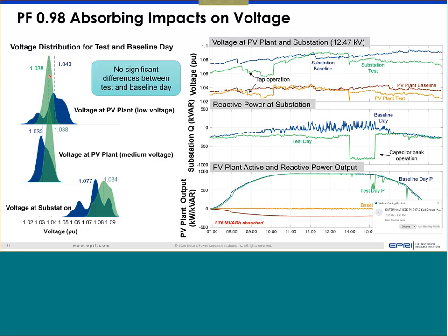Whether the same effect can happen on the medium voltage side, after you go through the transformer and with the other customers around it, how they behave. In this particular case, you can clearly see that's not the case. On this medium voltage side, yeah, it tightened the voltage, but it does look like the opposite direction. Rather than voltage lowering, it looks like it's still on the high side. The main reason is that it's 2 different days. The other day maybe the total load was changed or a different type of load condition was there. So that's why in the real field, it's very difficult unless you do long-term analysis to see the direct impact, or do immediately 5 minutes before, 5 minutes after. So these are 2 different days, that's why it didn't match.